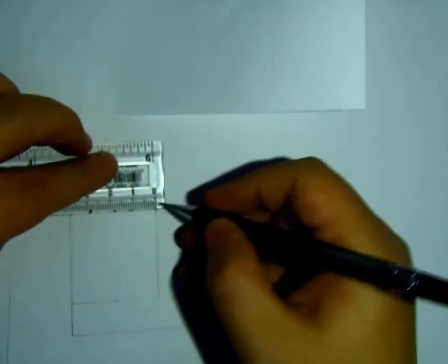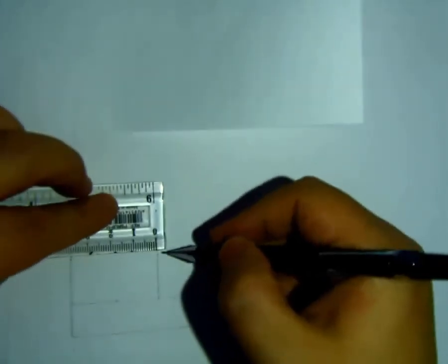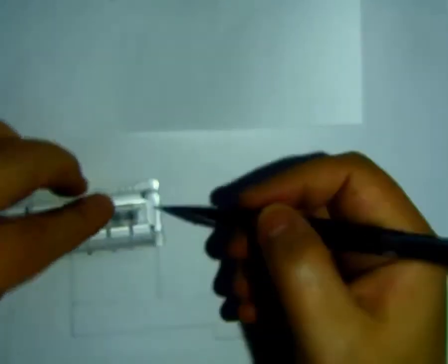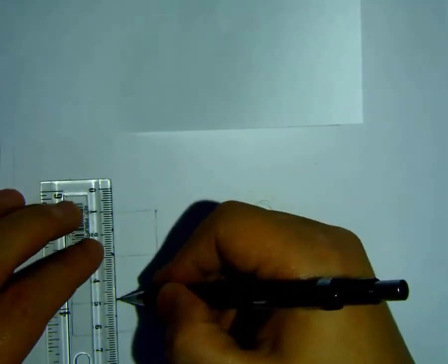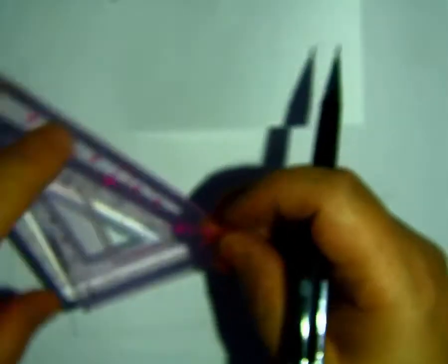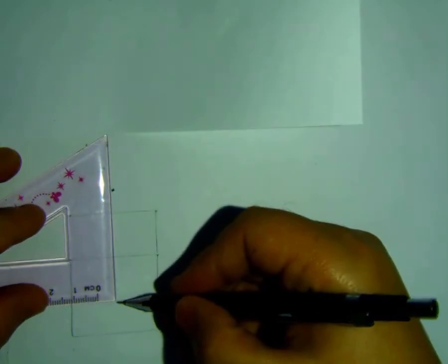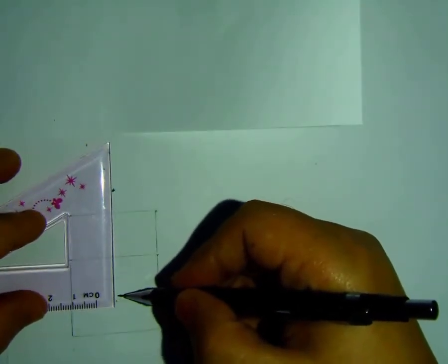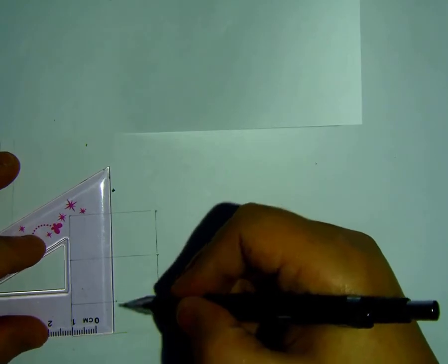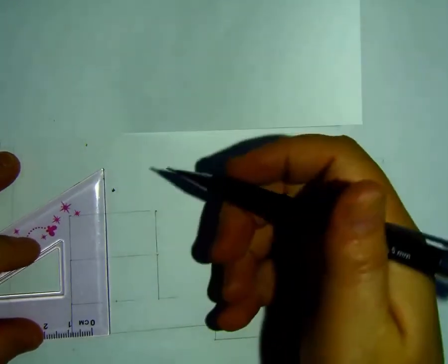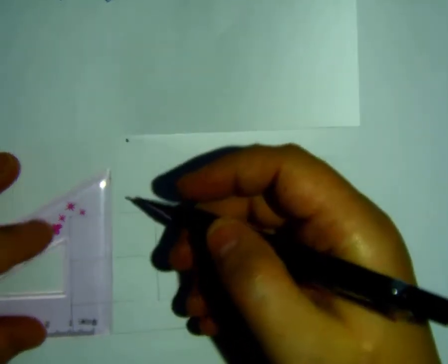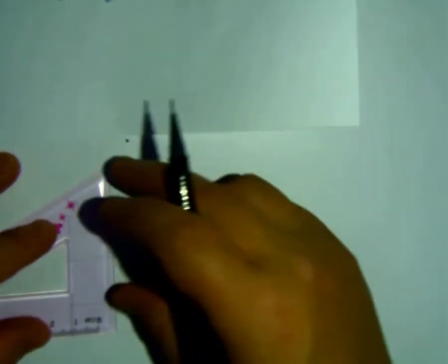And don't forget to draw thin construction lines like this. This will help you to determine the centers of the slot. And here we also need a perpendicular. If you are not sure how to draw a perpendicular line, you have to use a triangle. So put it like this. If you put it here, as you can notice, there is a radius here that will prevent you from being accurate. It's okay, you can put it on the lower one, and then you can draw the perpendicular from here to here, like this.